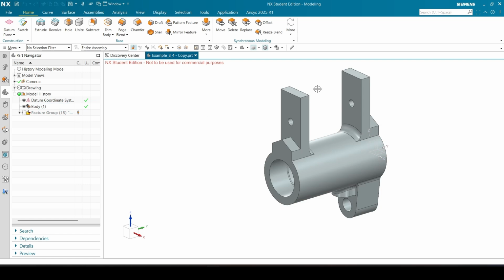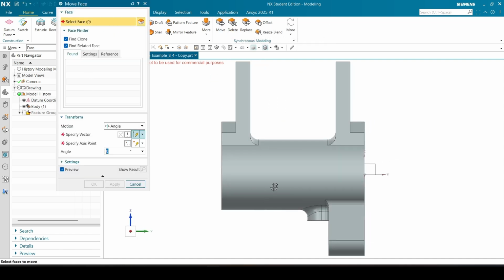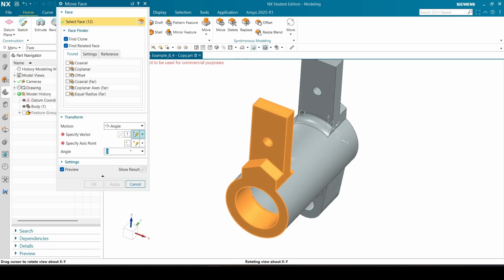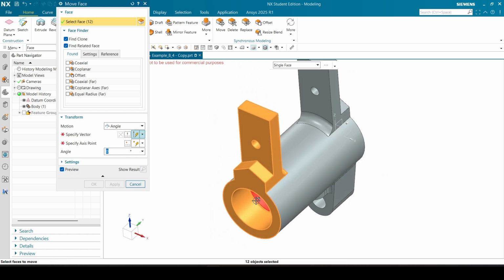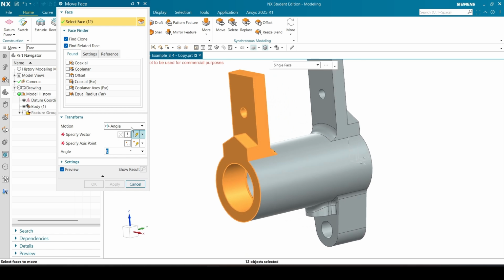The first big change is that this cylinder, this barrel, moves a lot forward. We will start with that. The easiest way is to orient myself to the right side, then say move, and select just all these faces over here. Then you'll see that everything, including that blend in the middle and the inside, is all selected. Now I can say I want it to be a distance